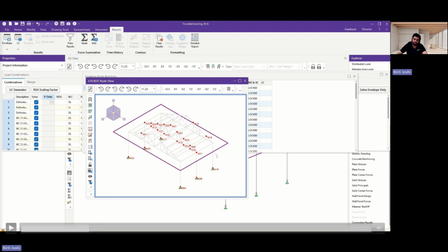In the column area, we have provided a pin in the member end conditions. We have provided the pin boundary condition, which has the rotational degrees of freedom released: MX, the torsion, MY, and MZ. Also we have member ends that can have member releases. So this kind of error may pop up at your fixed boundary conditions, and you might also have seen locked node issues in your code members.